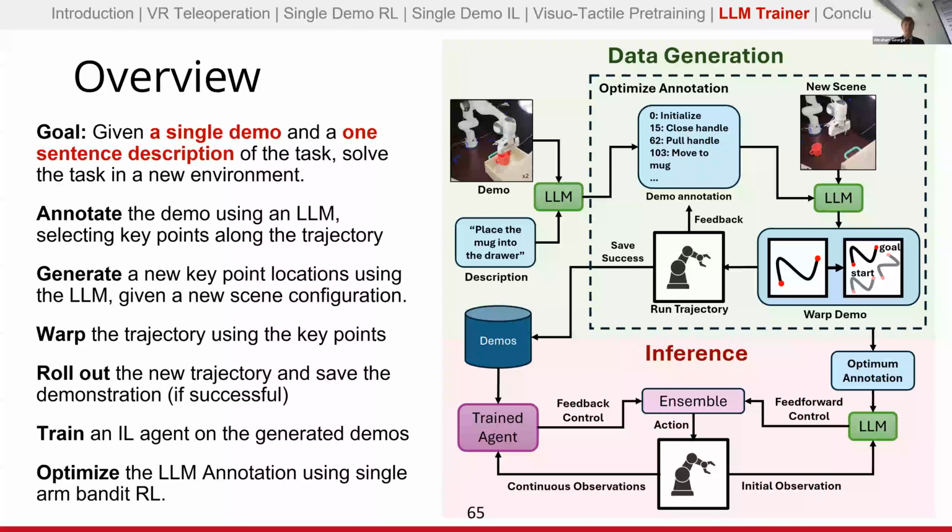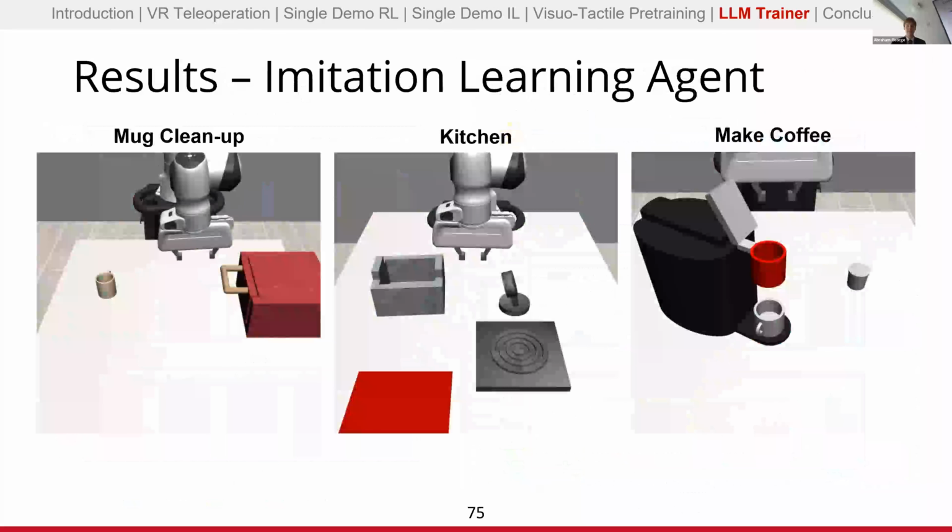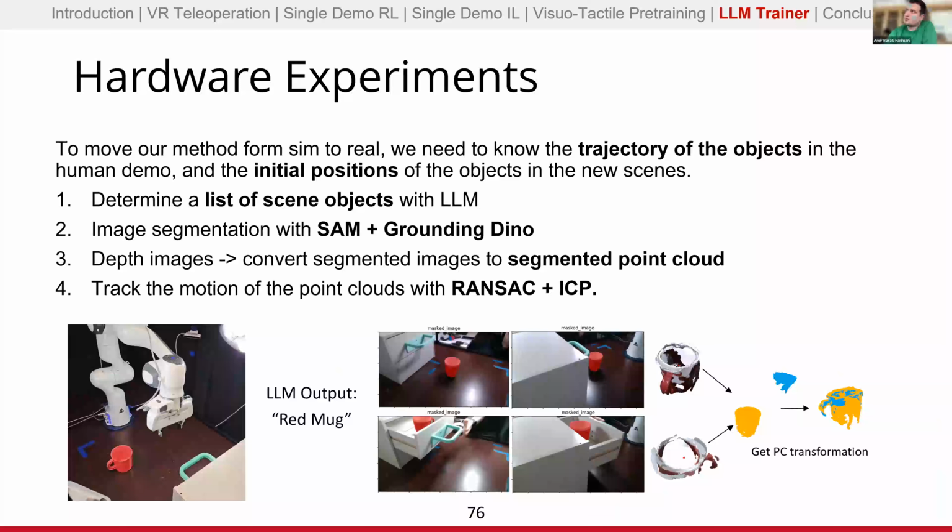That's not a problem. But for our method here for hardware, you start running into the issues of point cloud reconstruction. How well can we reconstruct a point cloud of the object and then do ICP and RANSAC? I think we got it within a centimeter of accuracy, but if you're trying to do cable plugging, like inserting a USB, 1 centimeter of accuracy isn't quite what you want there. Although, one more little thing is that specifically for the RL work, we care a lot less about accuracy. We could get away with a 20% success rate in reinforcement learning because we're learning that new optimal trajectory.